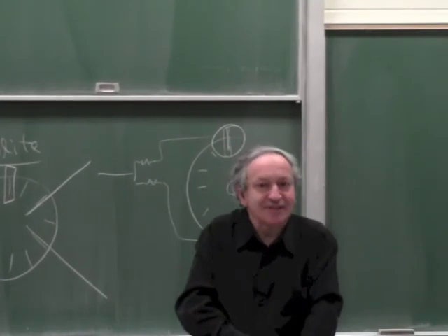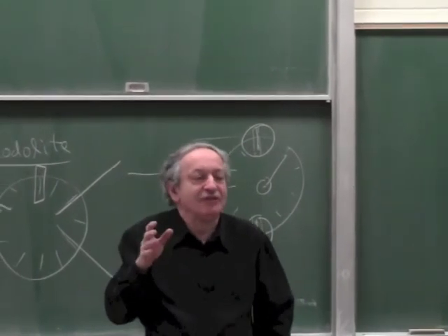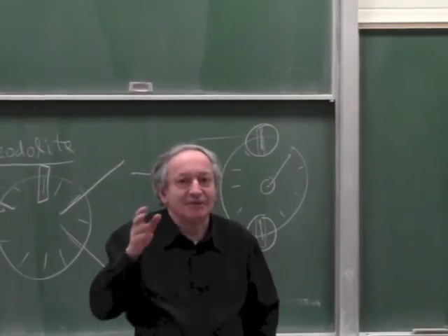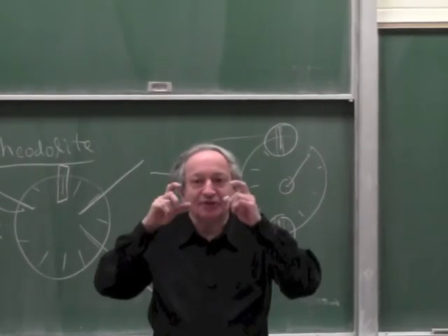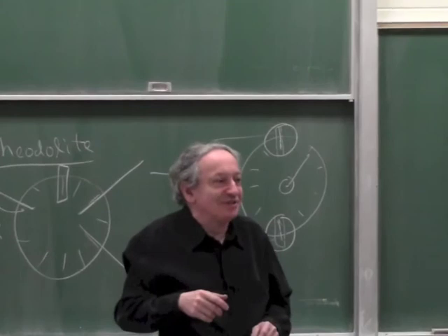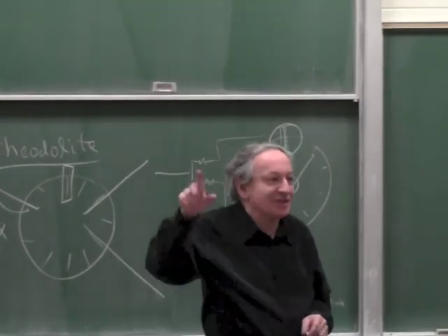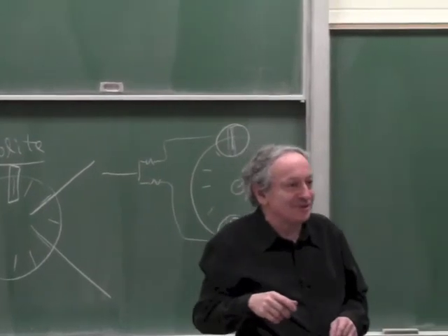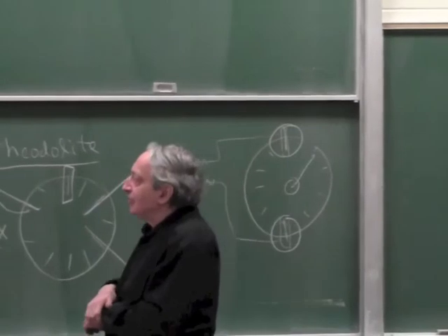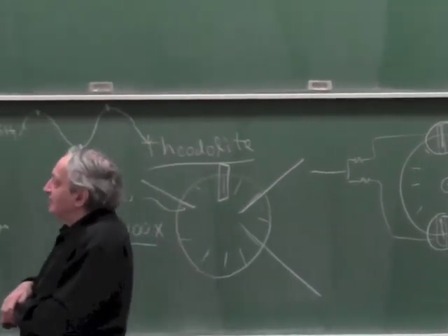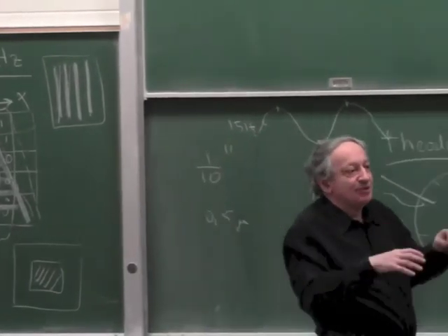But the camera itself, if you modulate the light at, say, even 50 Hertz, the camera will give you garbage. It's like what you get when you try to photograph a TV screen or a computer screen with a camera. You sometimes get half the screen in the picture because of insufficiently high sample rate. So the weak side of cameras is the very low sample rate. It's not suitable to sense high-speed motion.